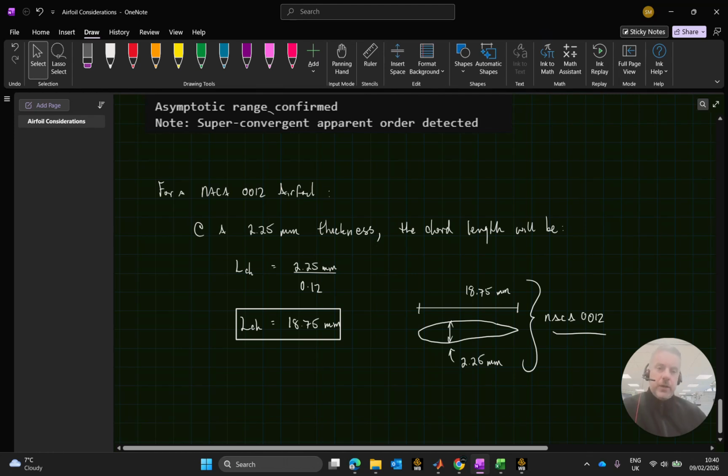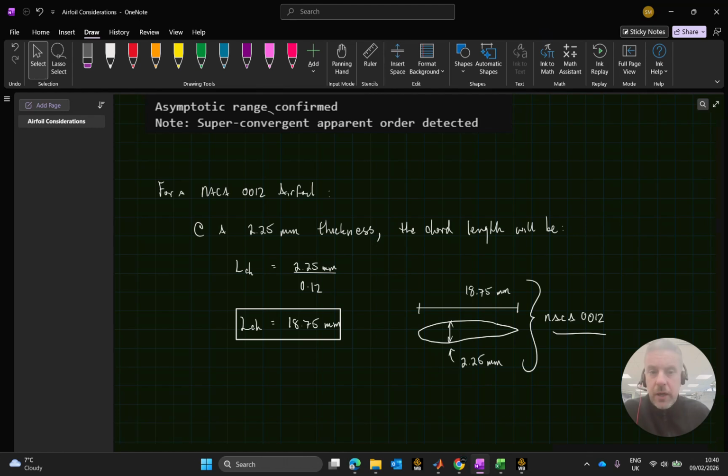And to keep like for like, so that when we do a comparison of the two airfoils, their drag coefficient and drag forces, we could say for this thickness, this is the drag force that we're getting. So clearly we're going to have less of a drag force for this one because we have less of a chord length, we have less surface area. So we would be expecting to see that, but we also might be able to take in other sorts of information from this, especially when we look at the contours and especially looking at the laminar separation bubbles.